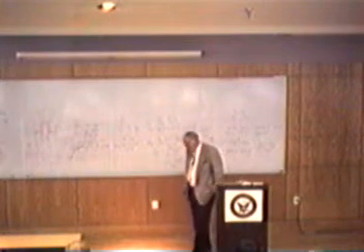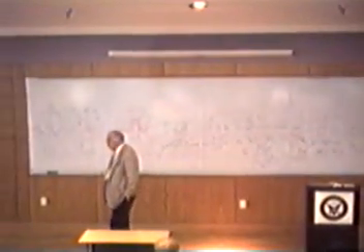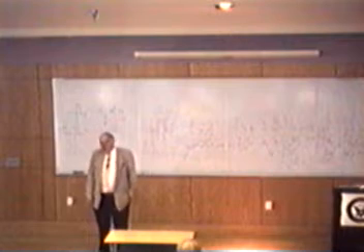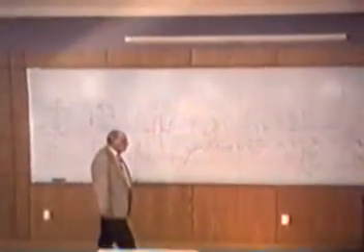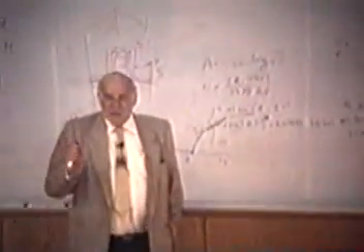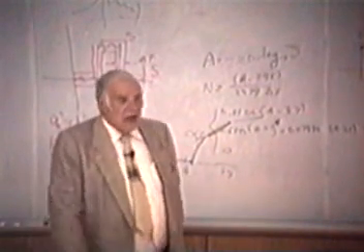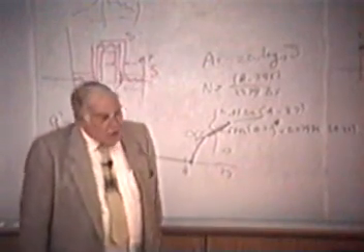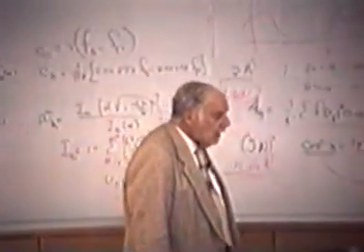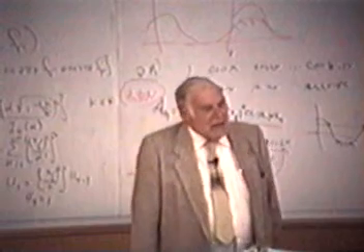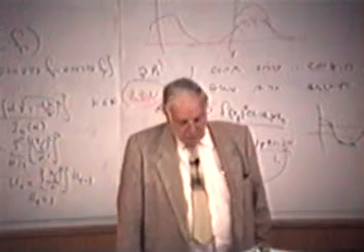So there's a general rule. The human ear is very insensitive to lots of things in the sense you can get the message through. All you got to do is go to the airplane cockpit sometime and listen to the noise that goes on there, but the pilot can understand it. On the other hand, you've only to listen to a skilled musician to realize what finest discrimination the human ear can do. It can both get through vast amounts of noise and it can make very fine discriminations. And so when you're dealing with a matter, you've got to ask, which of the two am I in? If I'm in a hi-fi trying to fool the human, I've got to pay a great deal of attention to phase and so on. If I'm not in that position, I can pretty well dump a lot of the phase and pay attention to the amplitude only.